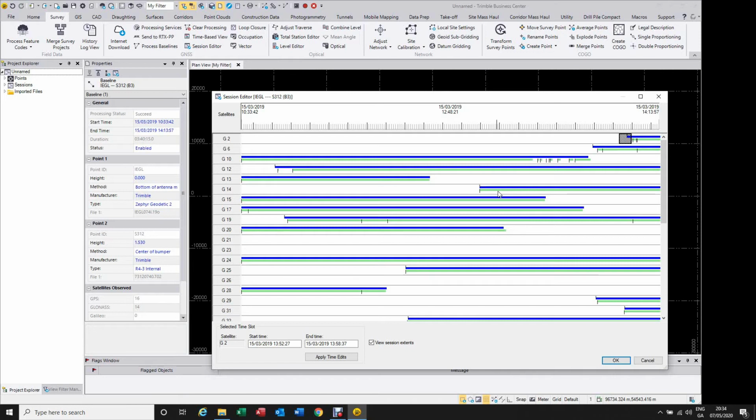how it works. If you have dual frequency, you can eliminate some errors and have a higher precision. That's how we achieve centimeter accuracy with the phase measurements, not only code on the L1. So one of them is L1, the other is L2, two different frequencies, and sometimes they're not 100%.